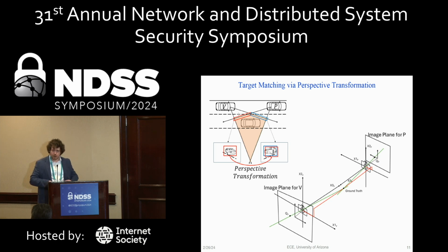However, we found in practice that when applying this perspective transformation, due to the accuracy that we needed in knowledge of these extrinsic parameters, which are the position of the cameras and the orientation, there were too many sources of noise in an application level to have reliable results. The sources of noise included driving on a rough road that would alter the orientation of the camera, or curvature in the road where the perspective was not maintained between both cameras.